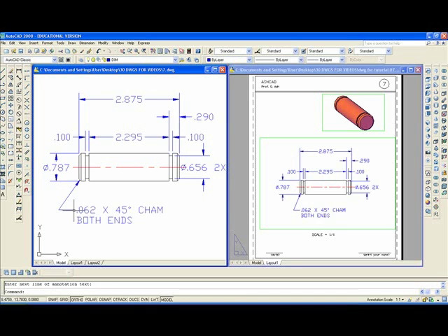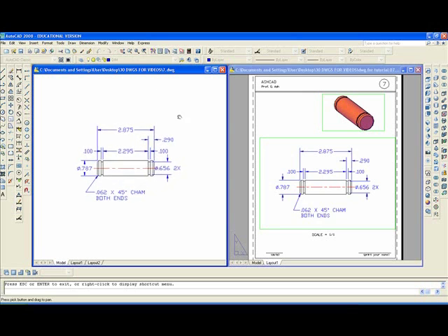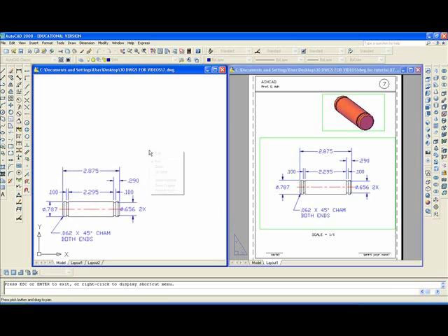And so it would seem that we have completed the 2D drawing on this project. Now what you want to do is to use Zoom Real Time and shrink that down, and then pan so as to get it to the lower left corner.